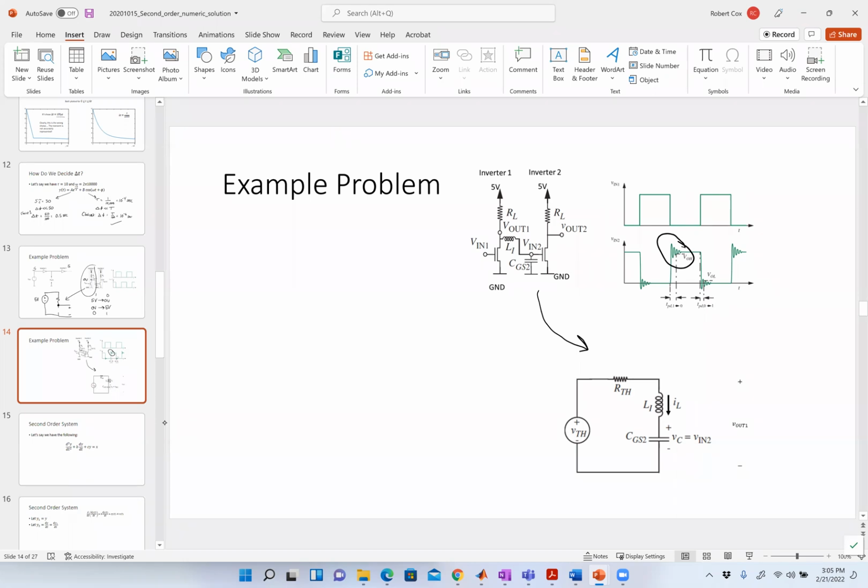Do you think that's desirable in a chip? It's not, right? Why would that be a bad thing, do you think, inside of a chip? Anybody know why that would be a bad thing? Because you get a lot of noise. You get a lot of noise, and potentially if the maximum voltage I'm supposed to have is 5 volts, what's really bad about that is that it's going above the 5 volts that I have, right? Depending on how bad it is, it could be 6 volts, 7 volts, 8 volts, right? That may be high enough that it causes failures inside the device. All right, so I need to make sure that's not there.